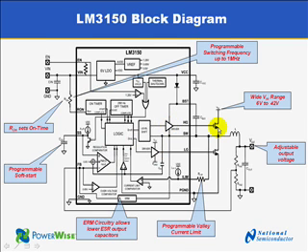The high side MOSFET is an N-channel type and needs a bootstrap capacitor to supply the high side driver. The device uses a low voltage internal voltage rail generated via LDO. This is buffered by a small output capacitor. The peak current in the inductor can be programmed by an external resistor. This block is the emulated ripple mode circuitry, which allows the use of low ESR output capacitors. This will be explained later.